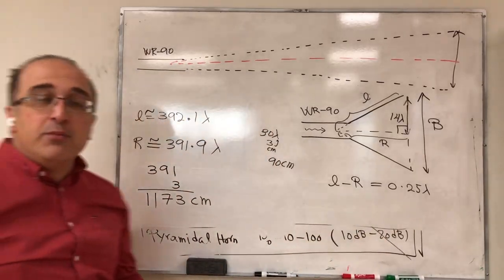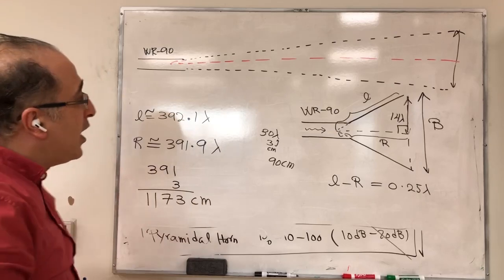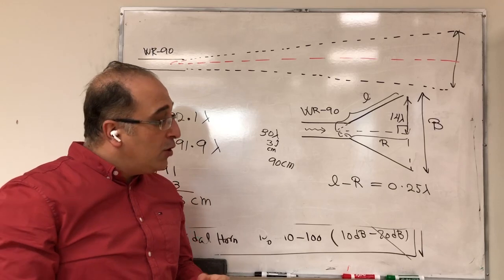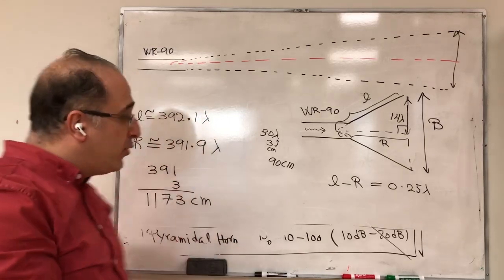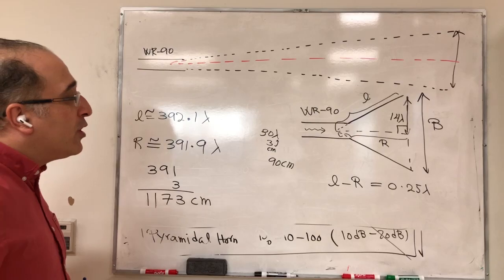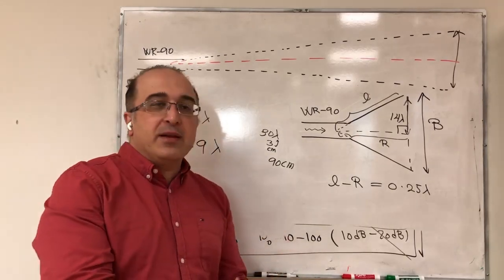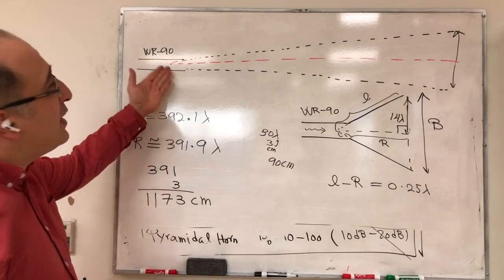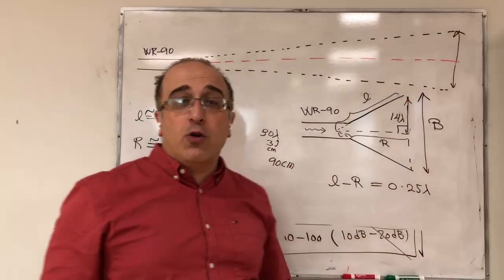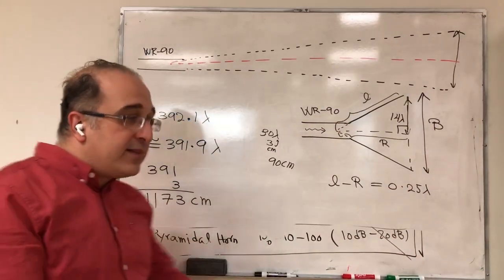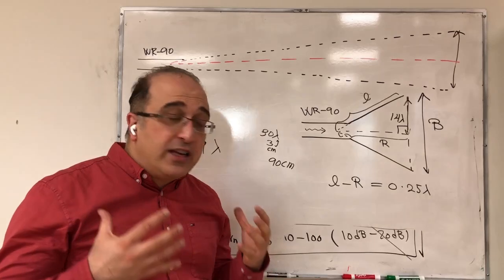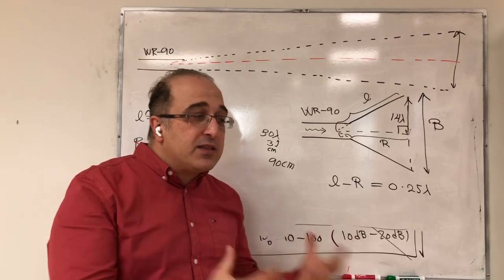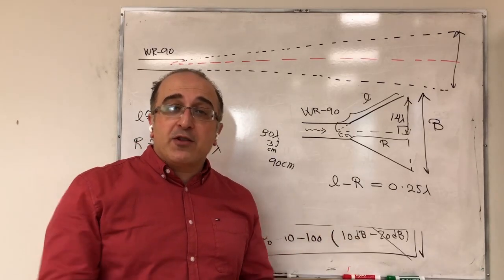So that essentially brings us to the problem of designing such big directivity with horn antenna. People have done that for different reasons, but for standard typical applications, if you want to use a horn for such directivity, then you pay the price on the length of your horn. So that's why we need a different antenna to get us to these huge directivities, like for example 40 dB, and that brings us to the topic of reflector antennas.